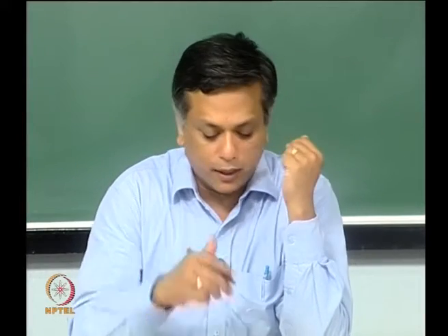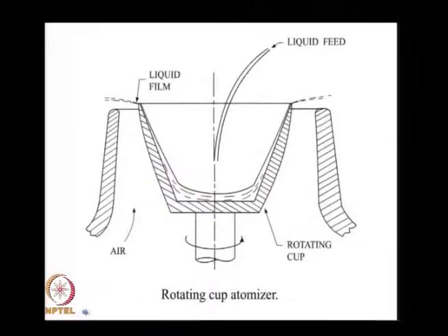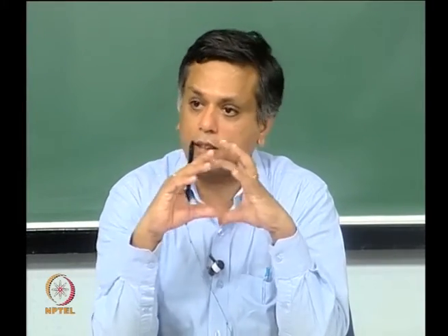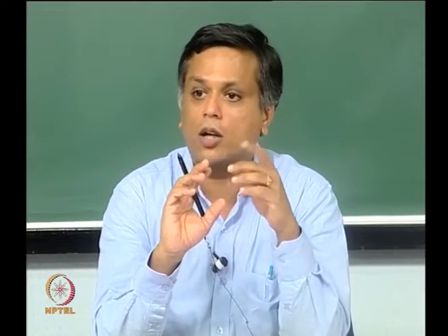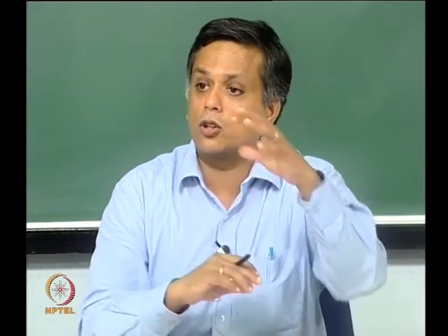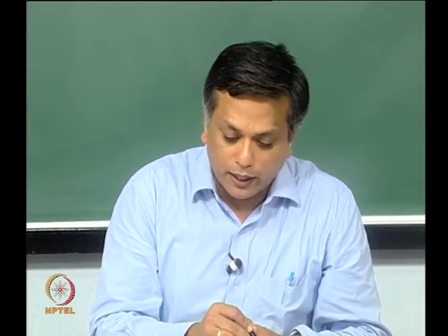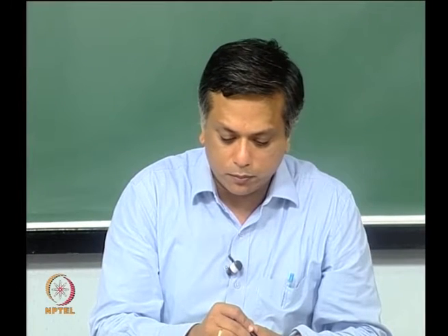In the previous examples where we were looking at external air mix, the only place where the air and the liquid come in contact is at that interface. That cross sectional area where the two are allowed to exchange momentum is very small in comparison to the total surface area of the liquid. Whereas, in the case of an effervescent atomizer,